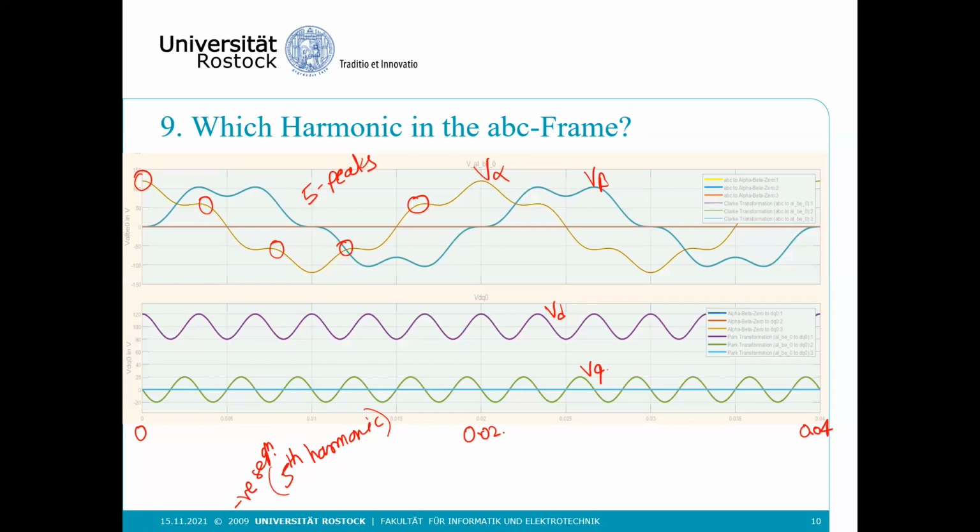The fifth order harmonics. In the fundamental you can have positive and negative, you mean 50 hertz fundamental, but in the harmonics, the fifth harmonic will always be the negative one. So the thing is, it's a three-phase system. I was also confused with that question, but I asked my supervisors before the second lecture.